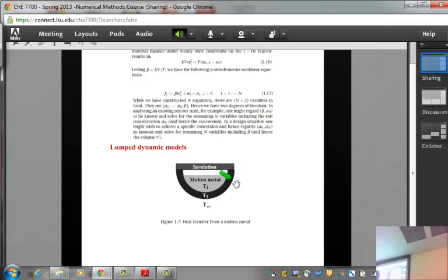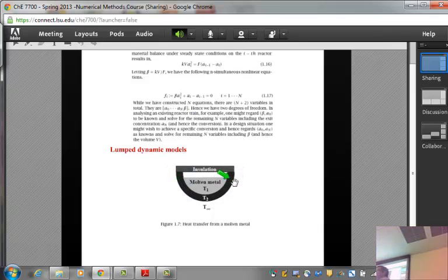T2, let me ask you the question. I just said that T2 represents the temperature of the crucible, some sort of a ceramic material that I keep, for example. T1, I argued, is a good approximation to say it is lumped because it's a metal, very high thermal conductivity. In T2, if I take the temperature at this point and at this point, will they be the same?